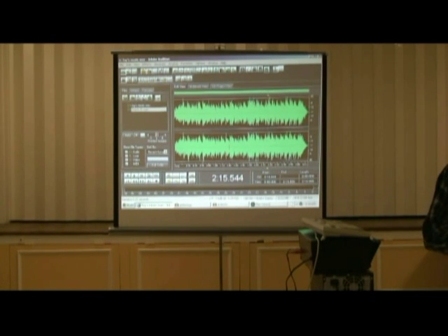I see nothing on here as far as whether this had Dolby or not. What setting did I use? I had Dolby turned off on this because I didn't know if it's Dolby or not. I didn't hear a lot of hiss, and the highs didn't set. Yeah, to answer your question very simply, yes. If it's recorded in Dolby, play it back in Dolby. Whatever you would normally play it on, play it that way.